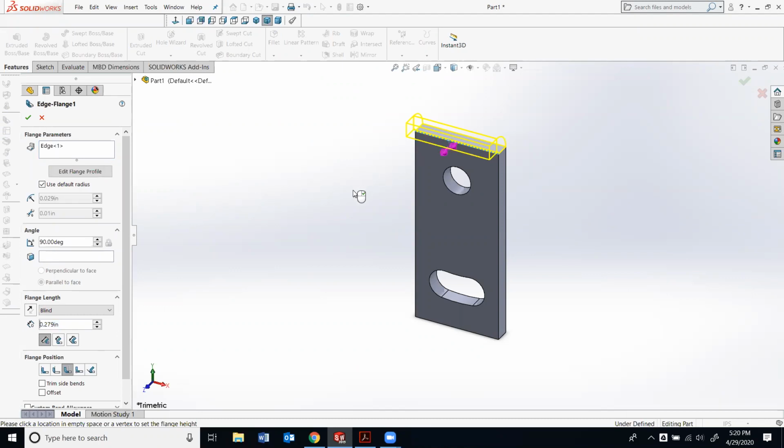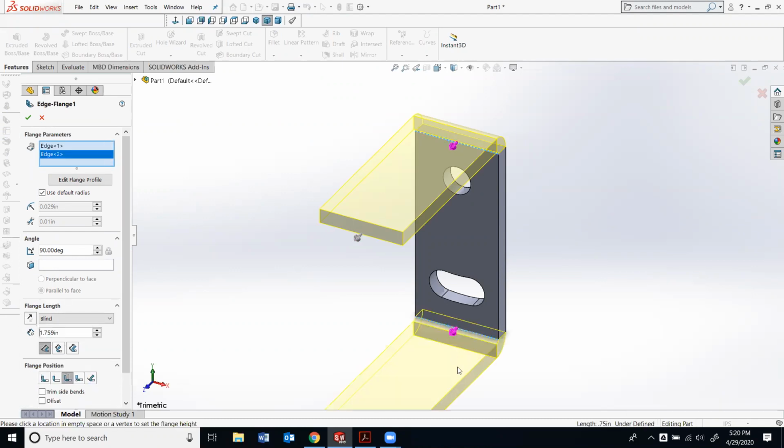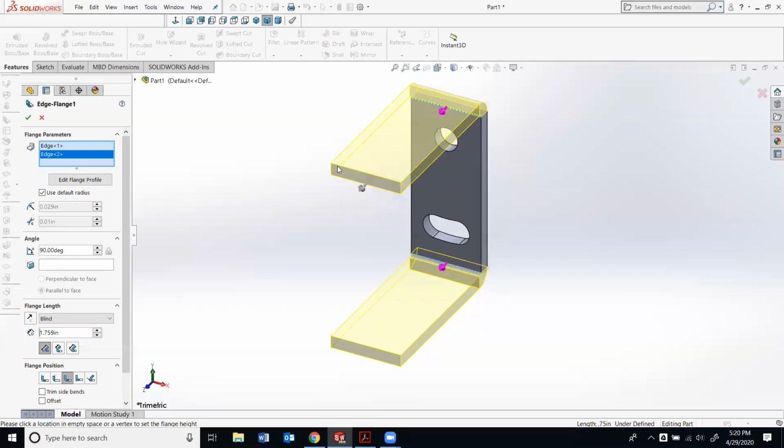Click on that corner and drag it out a distance. We don't really know or care the distance right now, but just drag it out some length and click, place it down. And click on the bottom front corner. And it will automatically come out the same length you made the top. Okay, so that was clicking on there and there. Don't hit OK yet. There's more we got to do.